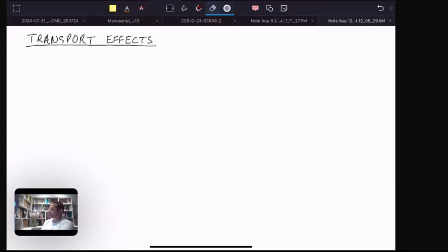Okay, let's dive into our discussion of transport effects on chemical reactions. So in all the lectures before, we focused on molecular scale reaction mechanisms and their intrinsic rate laws, with no external transport effects. We formulated rate laws for homogeneous gas phase chemistry, for solution phase chemistry, and for surface reactions in catalytic processes. For homogeneous reaction chemistry, the intrinsic rate laws that we've already learned can be seamlessly integrated into larger scale kinetic models, the kinds of reactor design equations that you learned in undergraduate. For example, batch reactors, plug flow reactors, or stirred tank reactors with fluid components.